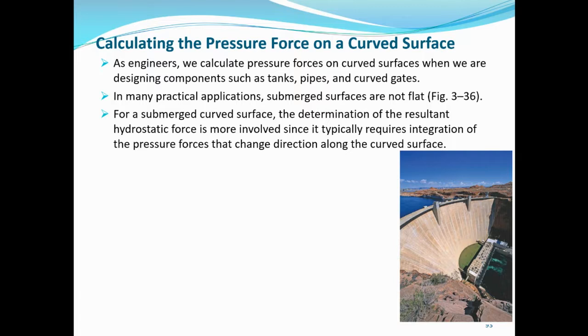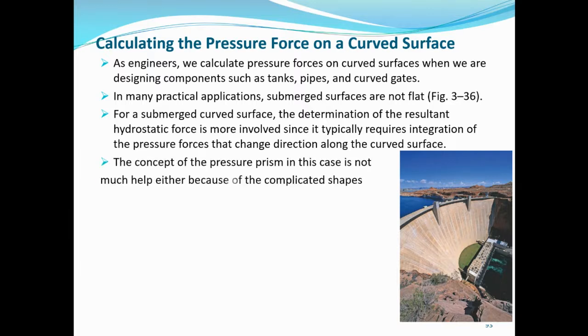For a submerged curved surface, determining the resultant hydrostatic force is more involved, because it typically requires the integration of pressure forces that change direction along the curved surface. This is very difficult to achieve. Hence, the concept of the pressure prism is not much help either, because of the complicated shapes involved.